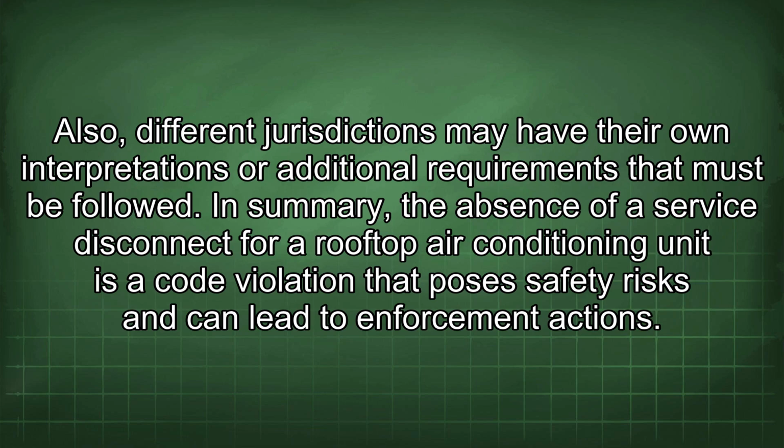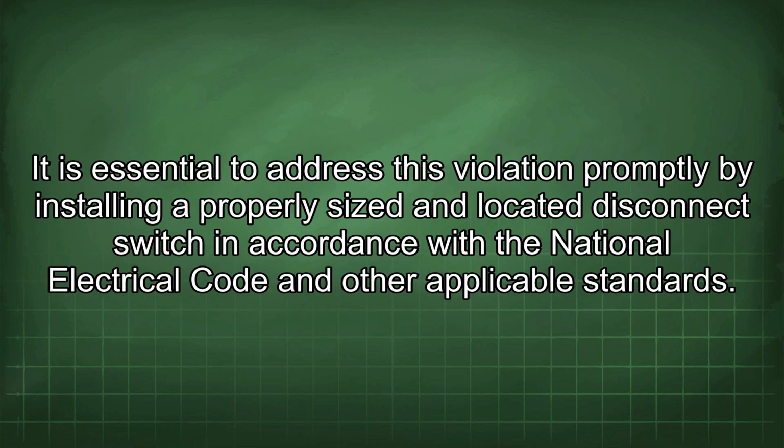In summary, the absence of a service disconnect for a rooftop air conditioning unit is a code violation that poses safety risks and can lead to enforcement action. It is essential to address this violation promptly by installing a properly sized and located disconnect switch in accordance with the National Electrical Code and other applicable standards.